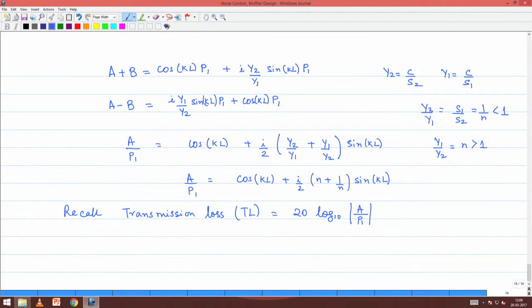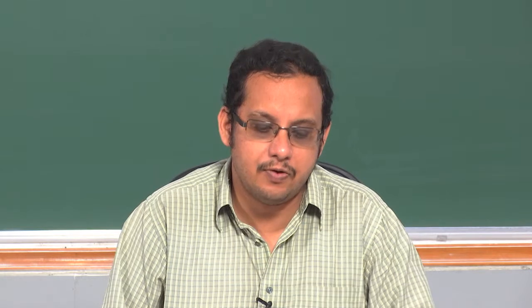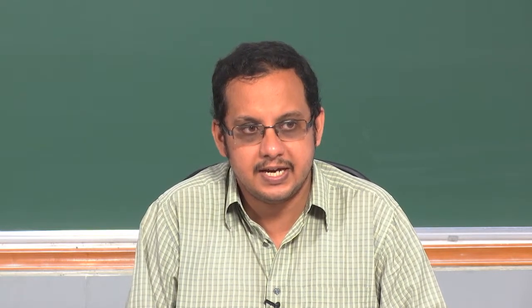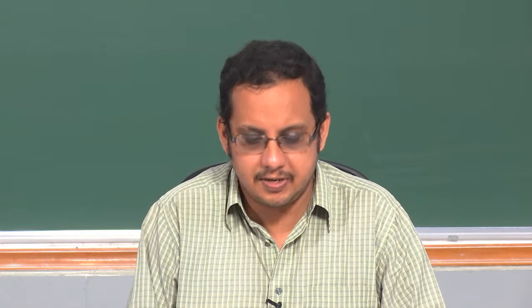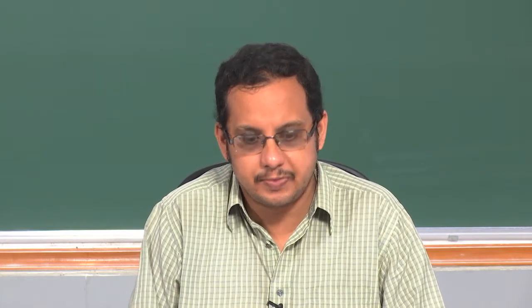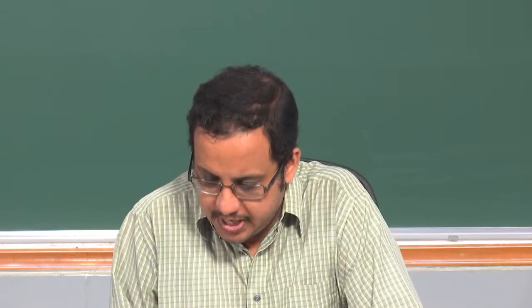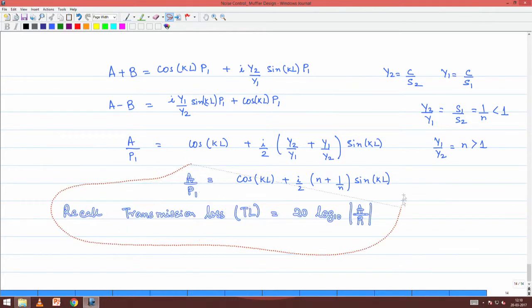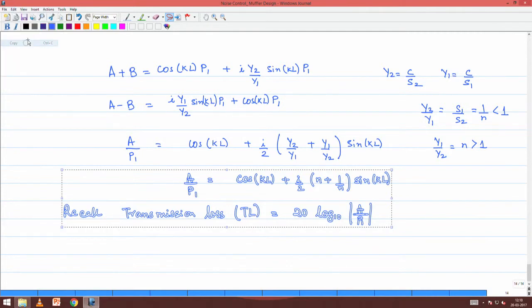So, now we see that we actually have sitting right in front of us the expression for transmission loss. Remember, we were unable to do this with a hand calculation in the case of method 1, wherein we took all the 4 or 5 waves, and it led to a system of 4 by 4 equations. We left it at that point, saying that the equations have been obtained and one can solve them using a computational package. But we are saying that the transmission loss can be readily given as a formula if we appeal to the transfer matrix method, which is the second method that we are going through. But more than the formula, what is very interesting to realize is that we will take some special cases out of this and try to figure out how the plot of this transmission loss will look.